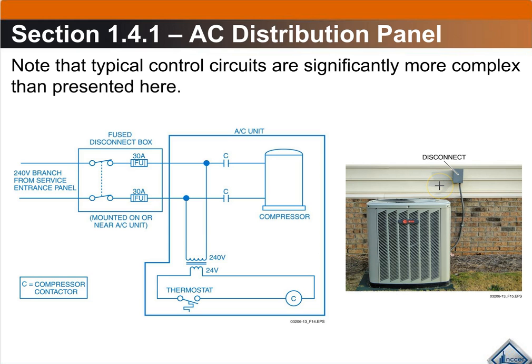The other thing, I always recommend that you check once you turn off the circuit breaker or pull that disconnect that there is no voltage present at the unit, because I have seen more than once systems that have been hardwired behind that panel that you can't see that bypass those fuses or that disconnect. So make sure that you stay safe when you do that.